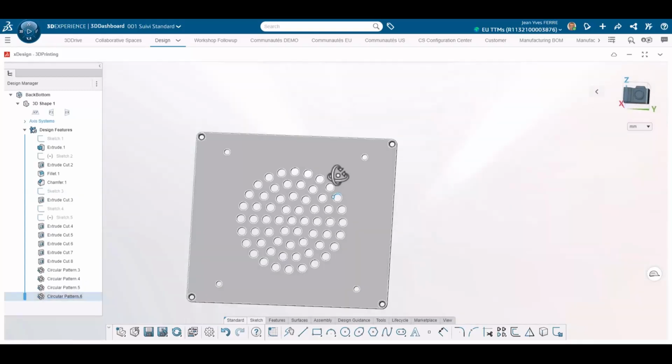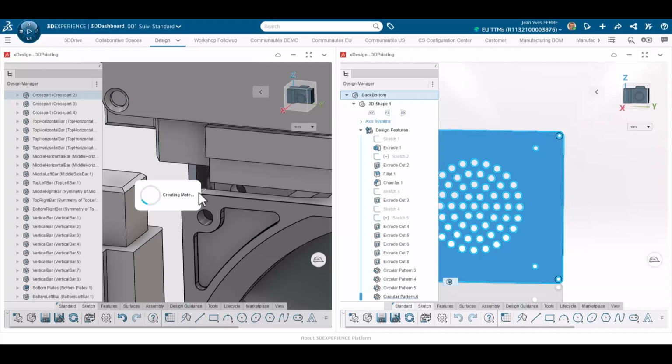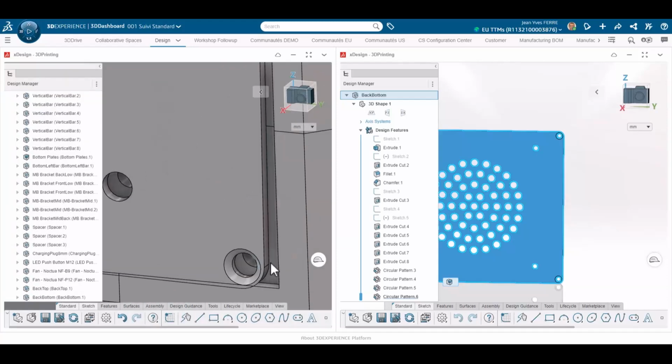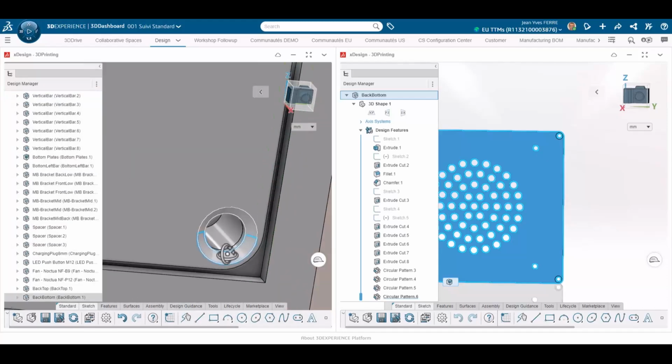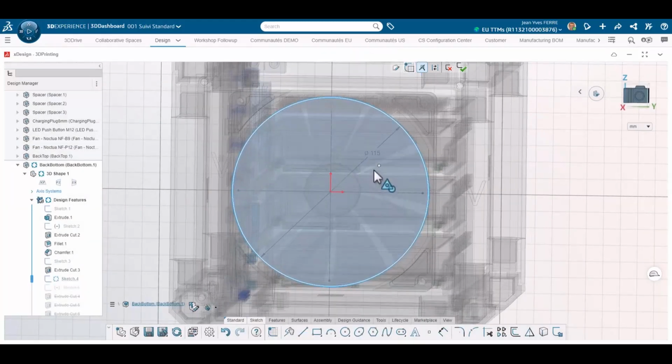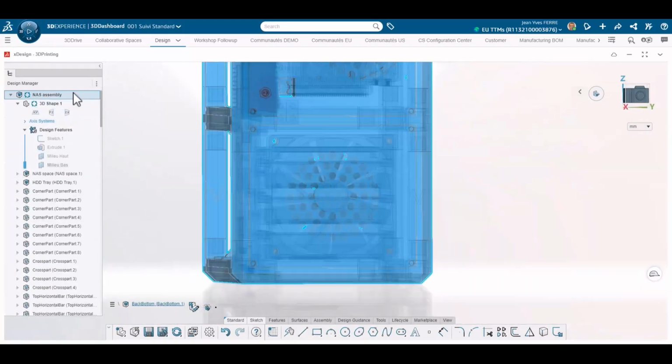To secure the bottom panel, after I place it on the planar recess, I locate it on a hole and add a parallel mate. Simple yet effective. No need to overcomplicate things. Next, I adjust the venting holes for the bottom fan. After reviewing the overall fan size, I realized that adding one more row of holes should suffice.